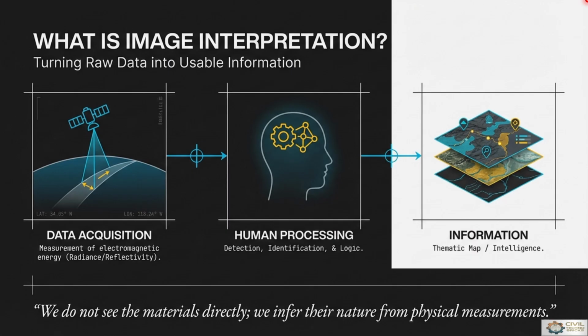Today we will see the core concepts related to the elements of visual image interpretation and its usage. Here, visual image interpretation is the process of identifying and analyzing the objects along with the phenomena present in remotely sensed data using their visual characteristics.